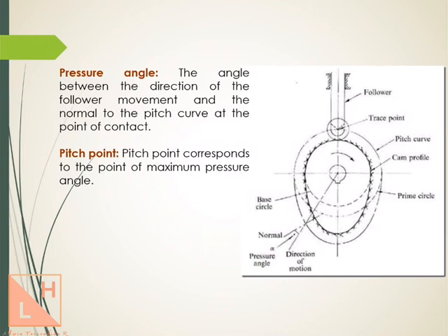Next is the pitch point. The pitch point corresponds to the point of maximum pressure angle. Like the position of the follower, at every point in the cam profile we will find different pressure angles throughout the contour of the cam profile. So at some points we will have the maximum pressure angle. Those points will be called the pitch point.